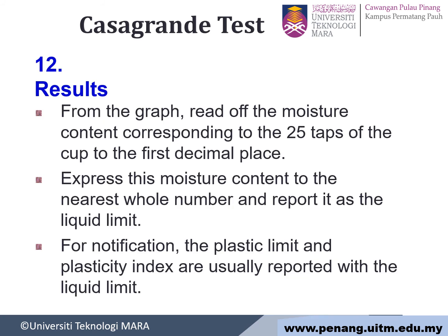Step number 12, result from the graph. Read off the moisture content corresponding to 25 taps or 25 blows to the first decimal place.